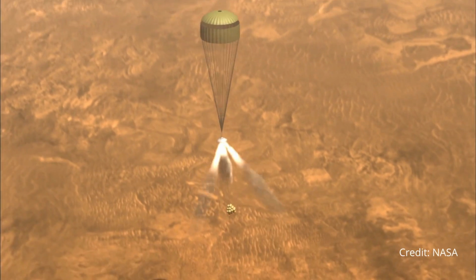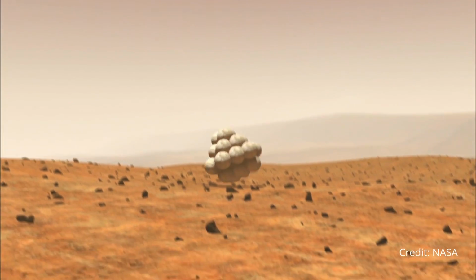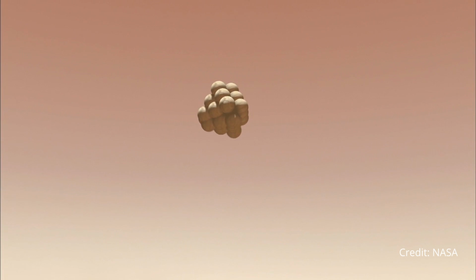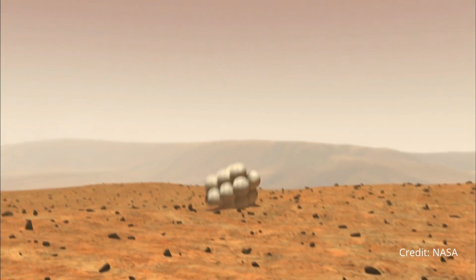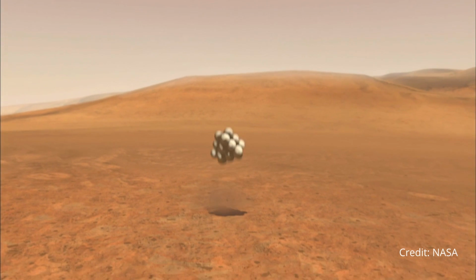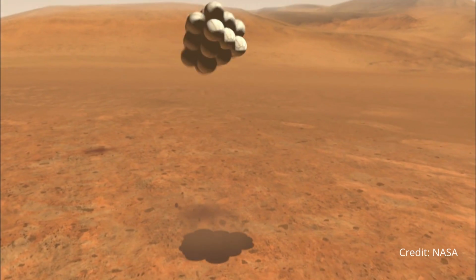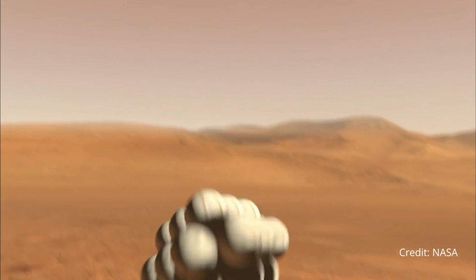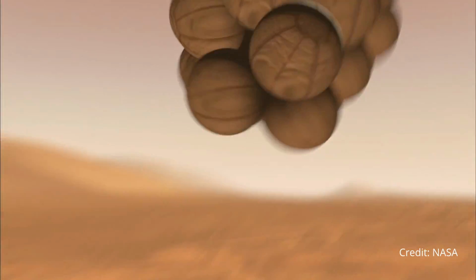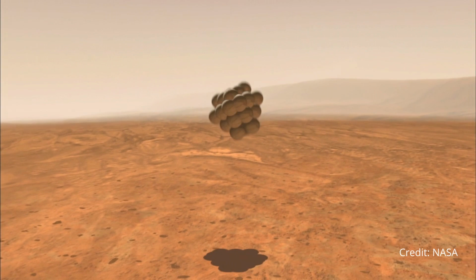Once the retro rockets were fired, they couldn't be turned off. Because of the uncertainty of the burn time of this kind of retro rocket, solid fuel rocket motor, there has to be a margin in when the payload is dropped to the ground. This then necessitates an airbag to cushion the landing because of the height of the margin. The airbag has its limits. The more massive the payload is, the higher the risk of the airbag rupturing on impact.